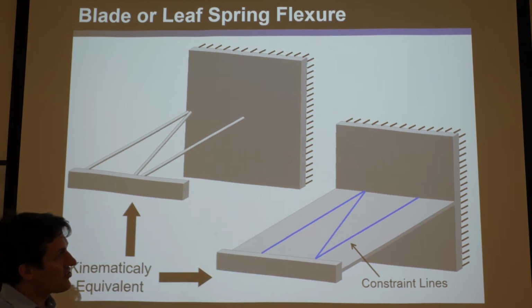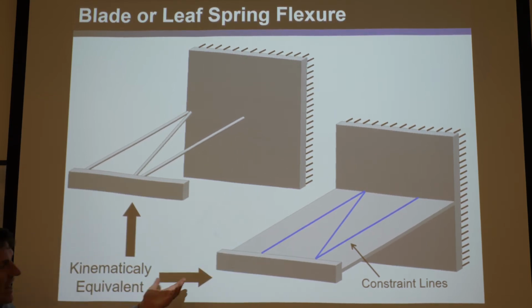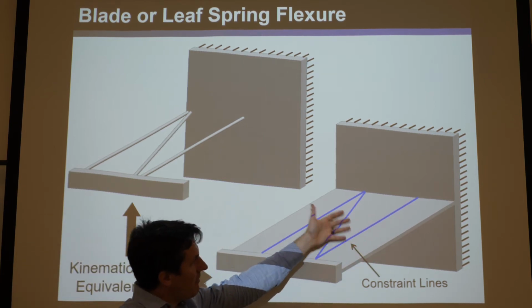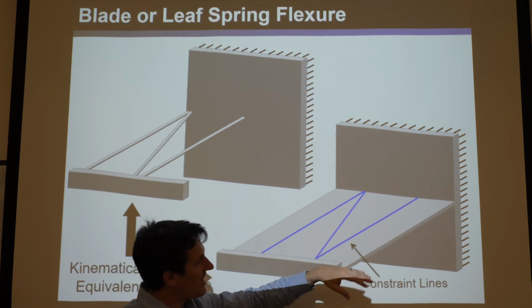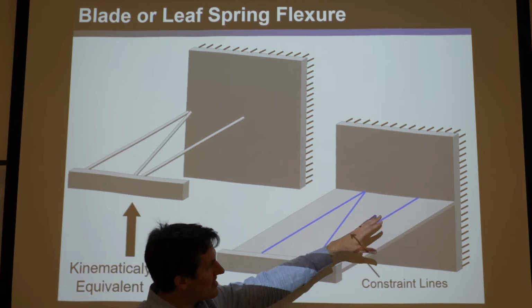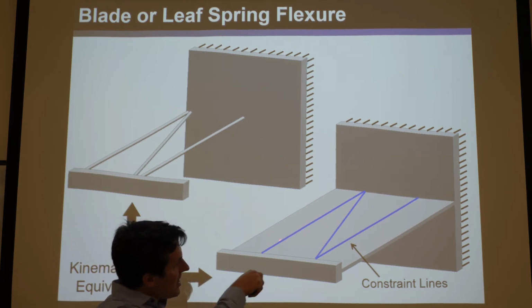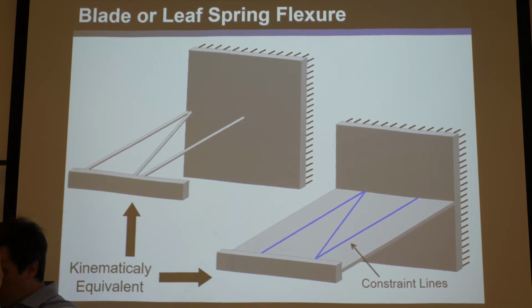This is more over-constrained. But because the blade is made of a single piece, I mean, no one would assemble infinite wires to make this blade, obviously. You'd cut this out of a piece of metal, or it would just be a shim that you'd get and you could assemble it in your system or something. But there's nothing assembled within the blade, and so the issues of over-constraint aren't that bad of just using a blade by itself, and it's just not useful to consider it to be over-constrained when you're using it. And that's true of any element, whether it's a wire or a blade or a notch flexure or anything. No element is by itself over-constraining itself.